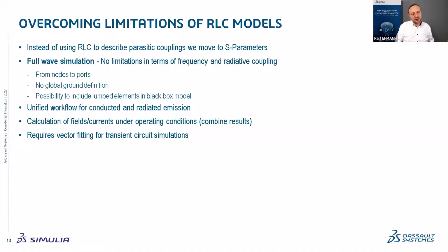It requires a step in between, which is called vector fitting, but that step is very well controlled, and we have capabilities inside the CST Studio to also perform this conversion from S parameters into a time domain SPICE circuit.